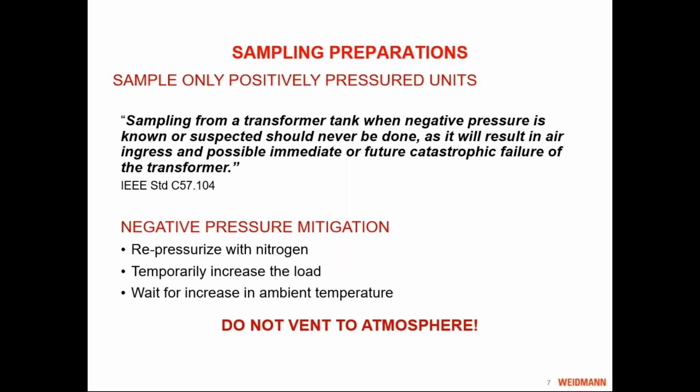There's really not a lot to taking samples, but there's one very important point, and you will forgive me, but this will get mentioned probably several times in my next 30 minutes. And that is, you should only take a sample from any piece of equipment if you can reliably determine that you have a positive pressure. I have a quote from the IEEE DGA guide that explains why.